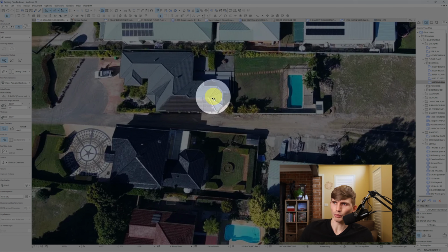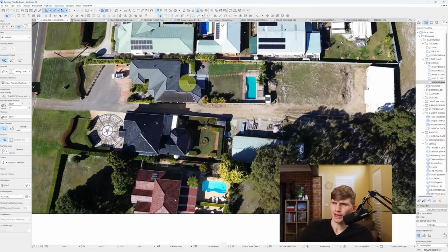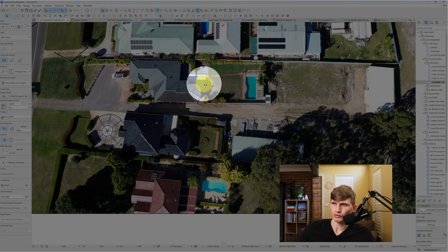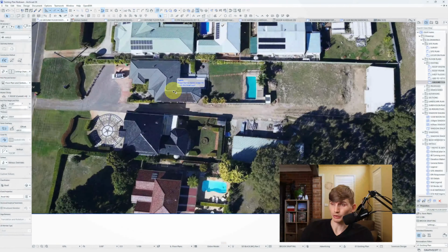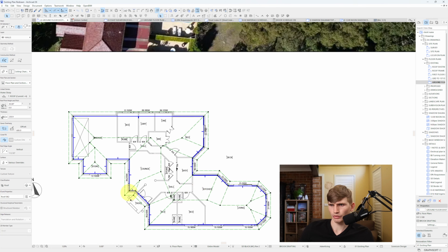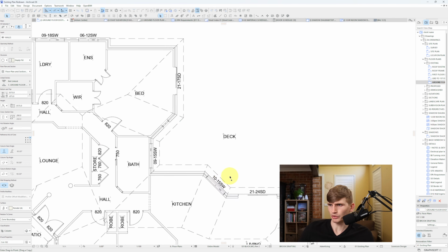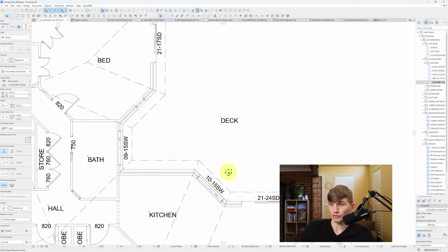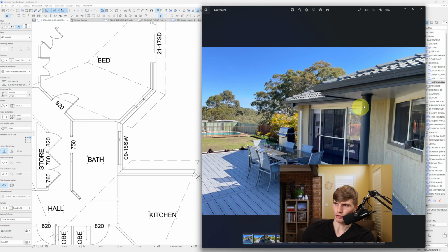You'll notice here that all the roof lines meet up to one central ridge. So we'll need to adjust this roof plane here accordingly. And this roof here is straight and it comes up to a ridge point just here. So we'll also need to adjust this. To adjust this, let's grab our post and chuck one just over here. This is in the existing setup. I'm not just adding in a random post. I'll show you in a sec. So it's this post just here. This post is picking up this portion of the roof, and this is going to simplify the roof plane itself.